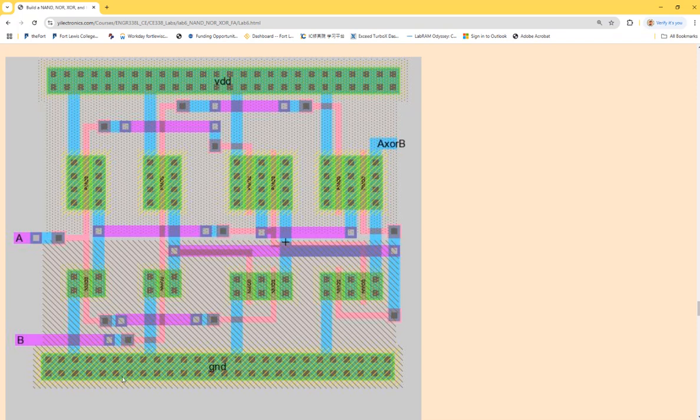So just directly build a via on the N-tap over here, actually multiple vias, and short metal 1, have a little metal 1 layer on top of the via to form the top rail, which is VDD. Yeah, you have to short all the N plus or N taps to VDD anyway, right?